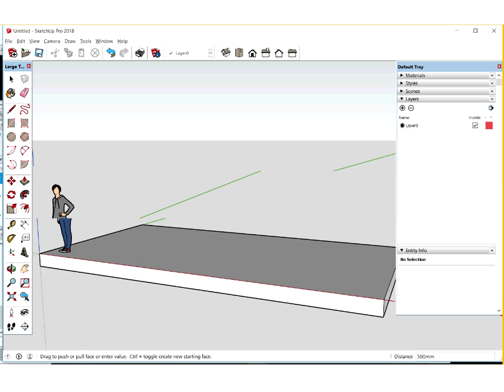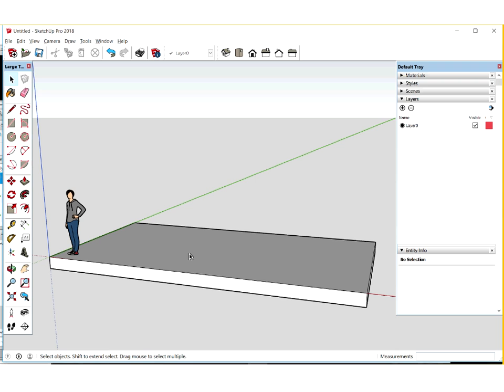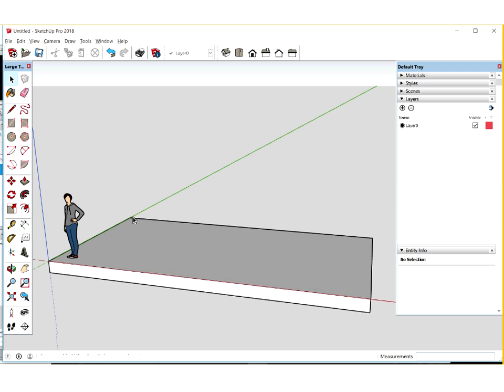Okay. So next thing we're going to do is group that together. My workflow for SketchUp, having learned this from some very experienced SketchUp trainers, which I found on their website, is to build something, group it together so that nothing else sticks to it, and then you do that with any object that you create. Build it, group it, and then once I've done a couple, we'll sort them into layers. Okay, so grouping and layering is the way to organize your geometry, and we only do all of these things to create, actually in the end, less work rather than more.